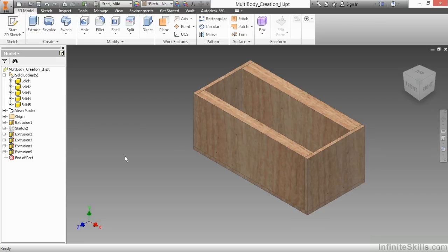Now, as I start to look at this, I start to understand as my design's coming together, maybe my model parameters need to shift a little bit. And currently, if I were to do this as separate IPTs to build this box, I would have to modify 5 separate part files. By going through a multi-body technique, I can change the multi-body file, and then that affects my other IPTs downstream after we go through that process of generating them.